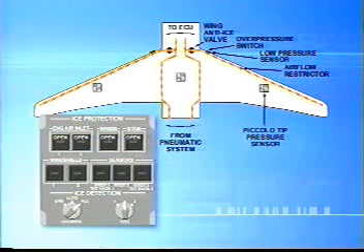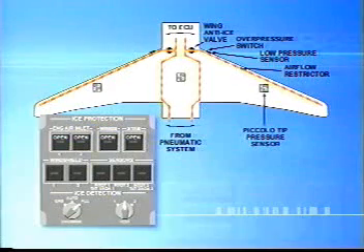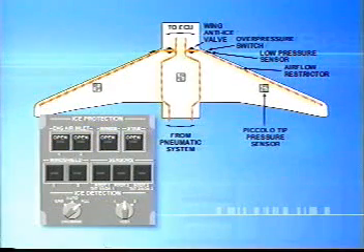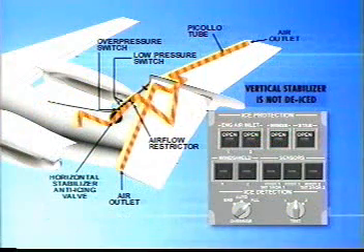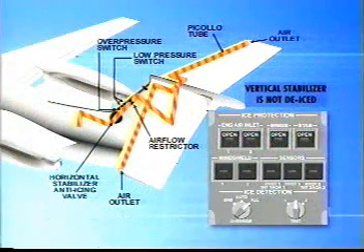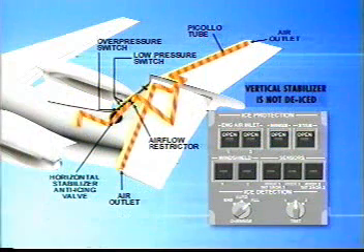When the valves are open, adequate bleed airflow is supplied for ice protection. Hot bleed air is ducted along the wing's leading edge by piccolo tubes, flowing through perforations to heat the surface. The same concept is applied to the horizontal stabilizer leading edge.